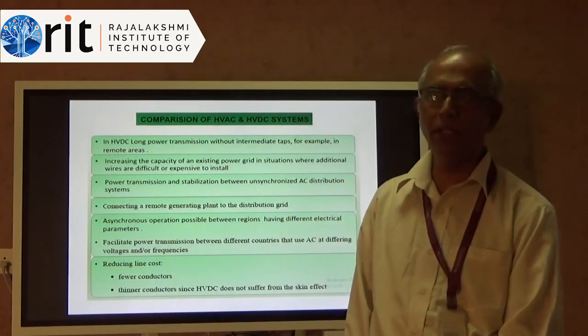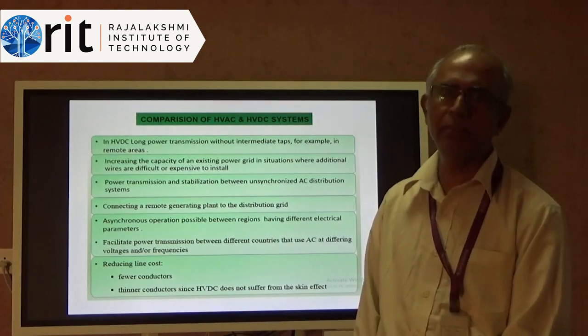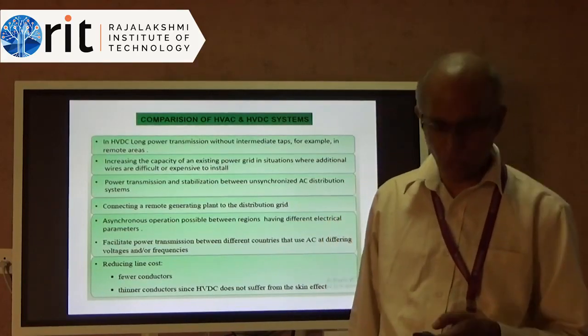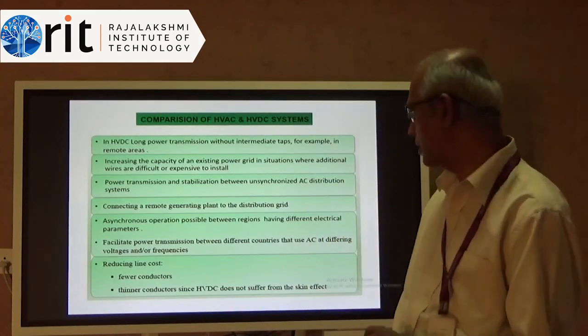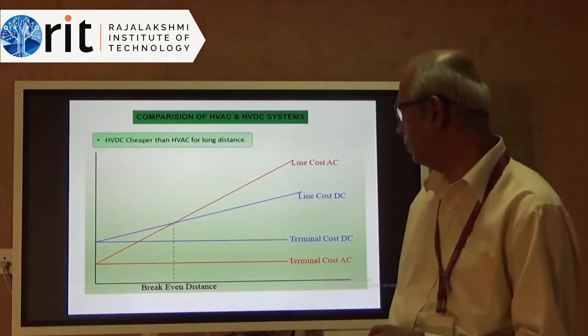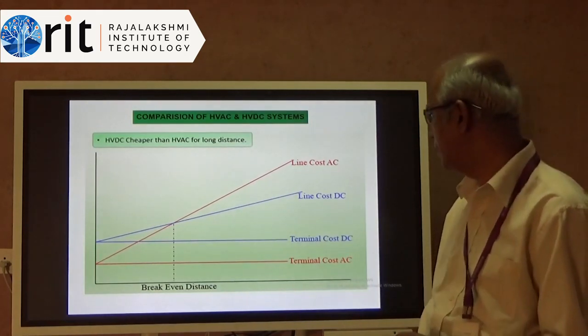Right. One major advantage which is going to come with HVDC is, we say the conductor cross section can be lesser. When you have an AC, instead of an AC you can have a DC transmission. They are going to substantiate it with some expressions which are going to say how the cost is going to reduce if you are going to have a DC transmission. So this graph will probably give you an overview how the relative cost economics works between AC and DC.